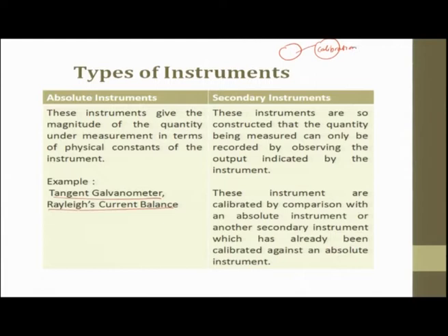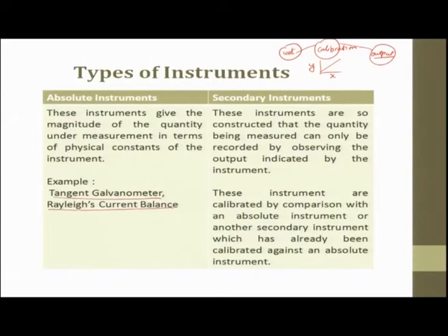This calibration will always try to take measurements in a linear relationship between y and x. You establish a relationship in this calibration, and then we try to get the output. The instrument we use over a period of time can have wear and tear, or even the first time you have to set the machine tension, the spring tensions or the other readings. So, what we do is we first calibrate. After the calibration is over, whatever we get is a direct measurement.